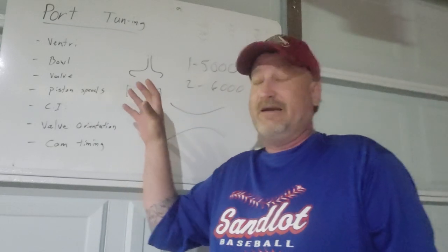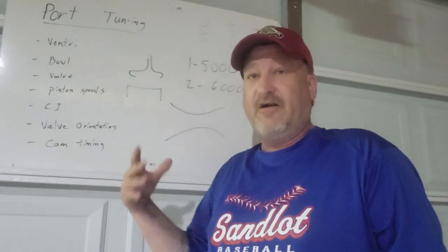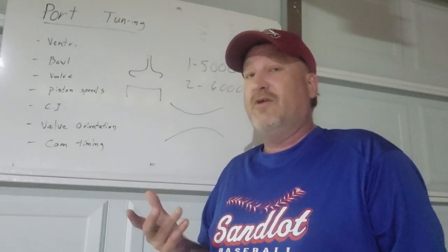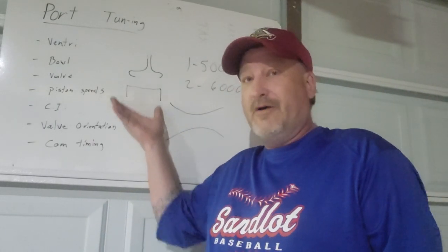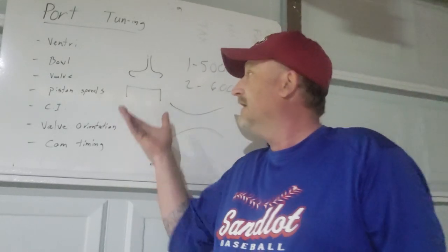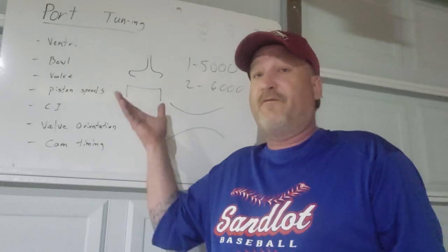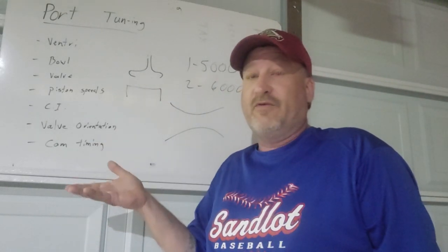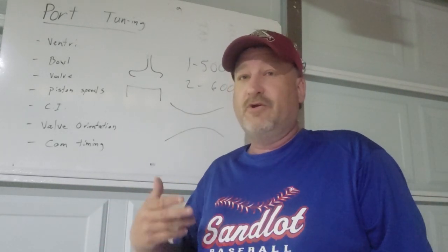The most you can get into there, in behind the valve within the bowl, is going to initiate the airflow sooner. And the bigger the cubic inch, the more vacuum it's going to create, without increasing the speeds of the piston through the stroke and so on and so forth. The shorter the rod and the shorter the stroke, the faster that piston is going to be traveling from top dead center to approximately halfway through its travel. So it's going to be a very aggressive vacuum creation.